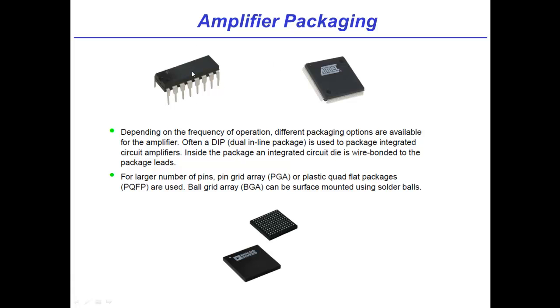So, Michel, you mentioned those wires on the inside. Those wires are made of gold, typically. Small amounts of gold, obviously. It's not a huge amount of gold. You know why we use gold? That's a good question. My guess would be that, first off, gold is a pretty reasonable conductor, and it's a noble metal, so it probably doesn't oxidize and age over time. That's true. And also, it turns out it's relatively easy to draw gold out into thin wires because it's pretty malleable. Oh, that's true.